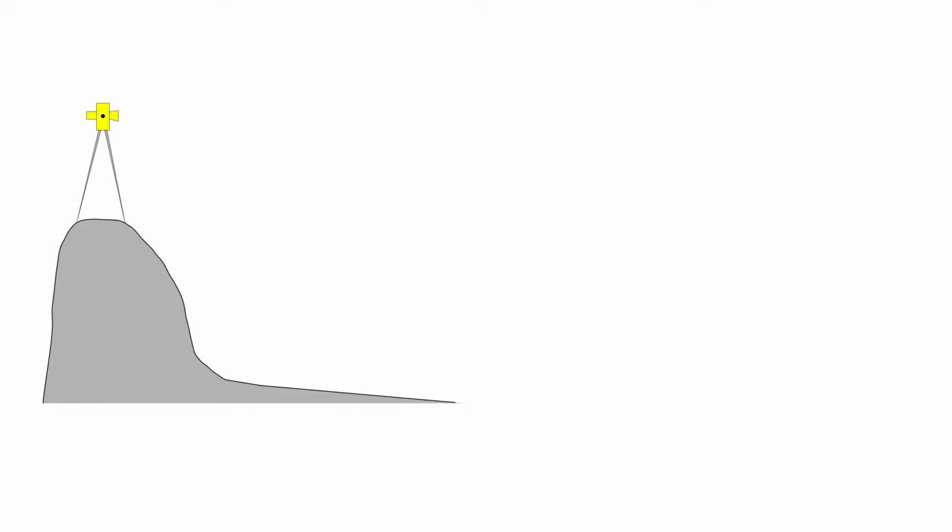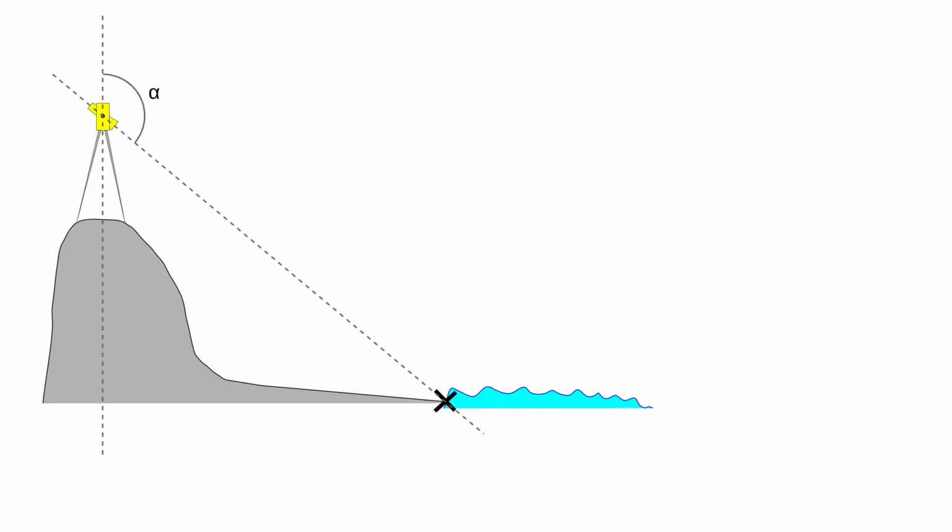The idea is quite simple: to choose a few distant points on the shore so that all of them are at the sea level and measure zenith angles to them with the Theodolite. Knowing the distances to these points and the measured angles, one can calculate the vertical distance of the points from the local horizontal plane of the Theodolite.